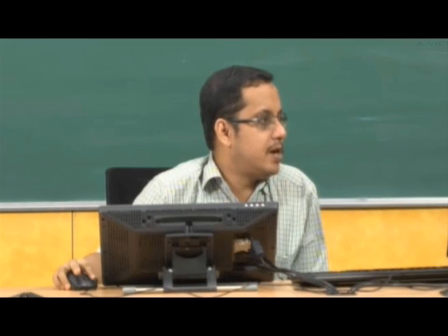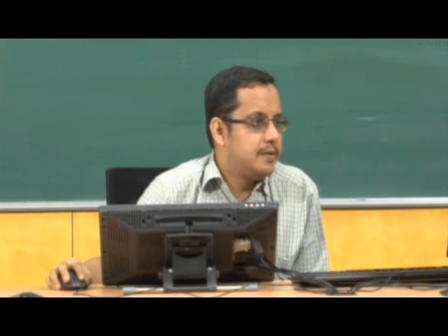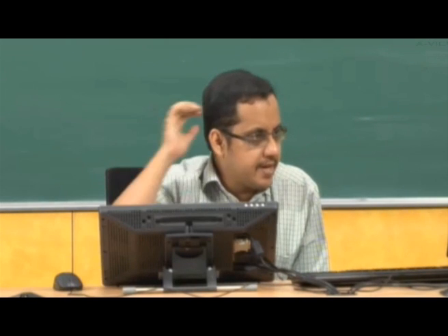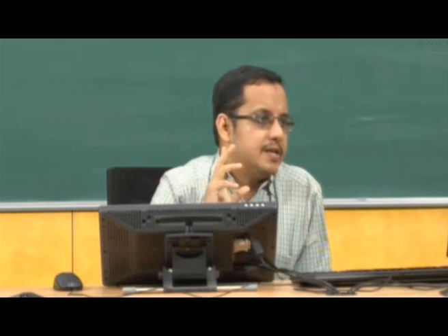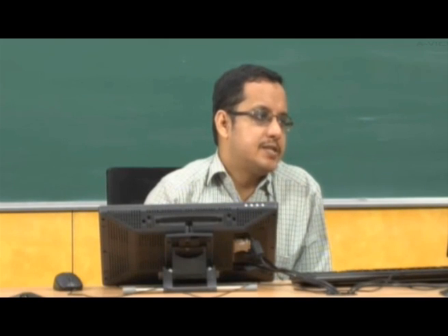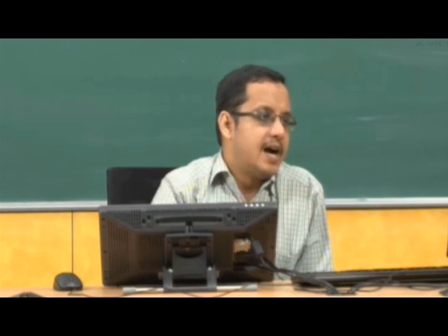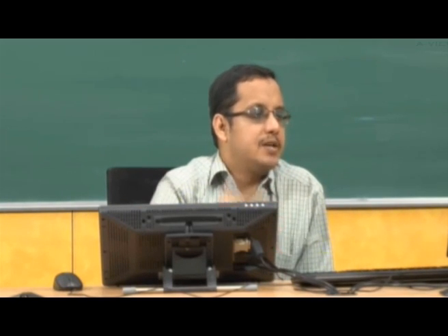CIT CMB, you want to ask me a question? Please go ahead. Good evening, sir. Good evening. How to figure out the primary crank and secondary crank in multi-line engines? The primary crank will be exactly the crank that you are seeing. Secondary crank is the crank which is at double the theta with respect to primary. So if your primary crank is making an angle theta with respect to the direction of your slider, then the secondary crank will make an angle 2 theta with respect to the direction of your slider motion. That's all. Primary crank is the crank which you are visibly seeing, right?